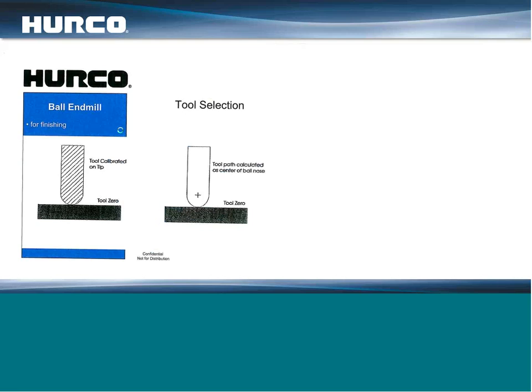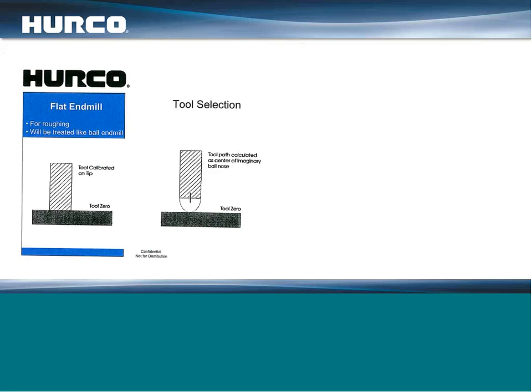Okay. Another quick question too, in your program parameters, your retract clearance, you said that's the only one it uses. What do you set that to? The retract clearance is the same as any other data block. What that wants to know is when you're moving or positioning from one data block to another, or with peck depth, how far do you want to lift above your part zero? So it's, again, just the safe region that you would use for anything else. A lot of people will set it to 1 inch or a half inch.